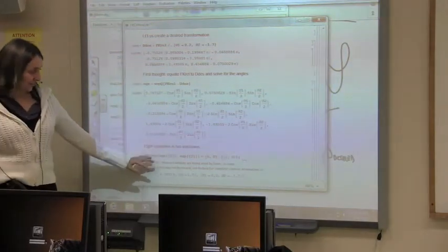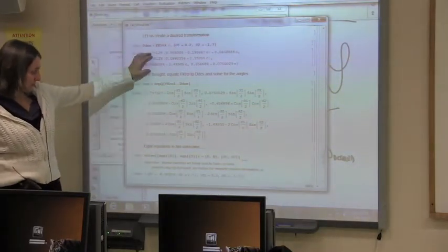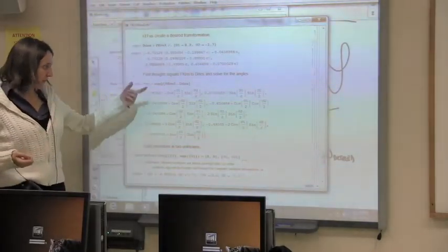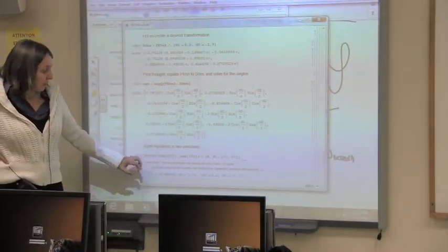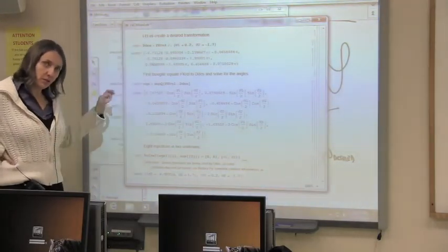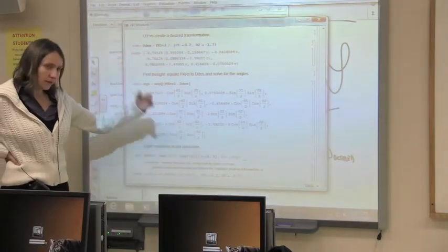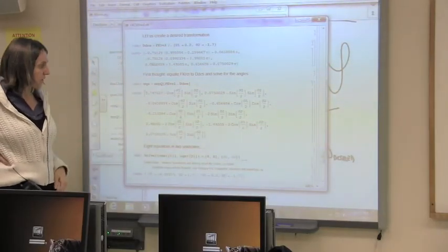But you see, this is the inverse kinematics problem. Given the displacement you want to attain, you get your angles. Now you put these angles in your robot and you can get this. And the same that we do for a point, you can do for a whole trajectory. This is the motion I want in my end effector. Let's see how I can go back to the motion in the joint space.